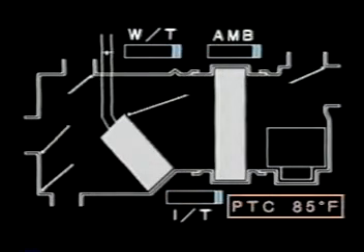Next, let's press the auto switch, and then let's look at the condition when the temperature is set at 85 degrees Fahrenheit. Immediately, the automatic air conditioner tries to heat the vehicle interior because the ambient temperature and the in-vehicle temperature are low, and there is a large difference from the set temperature.